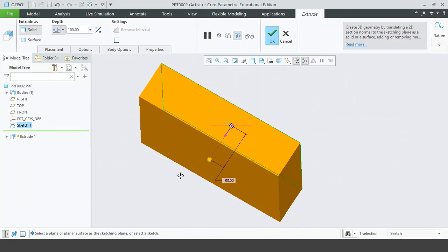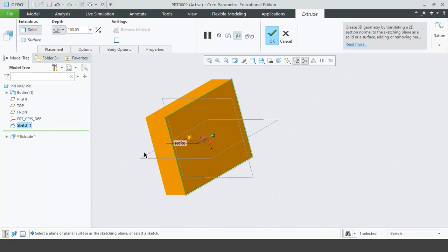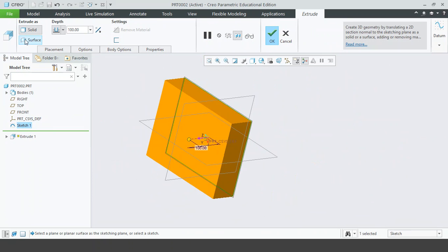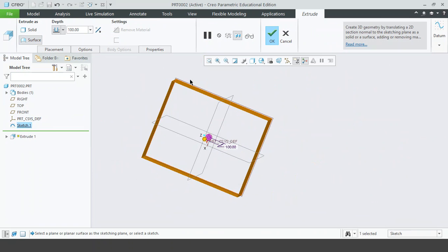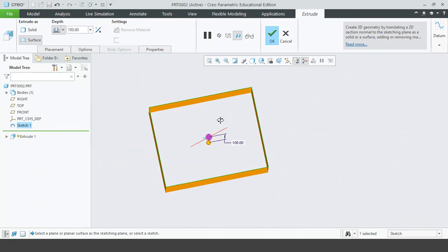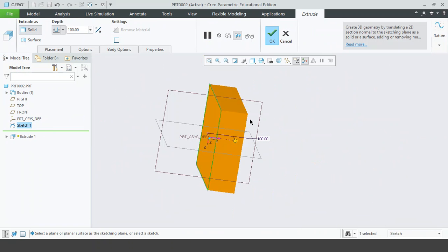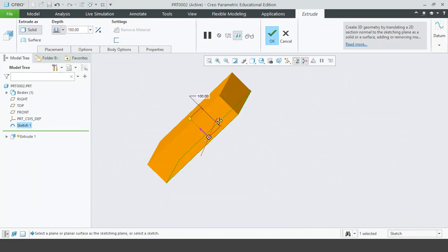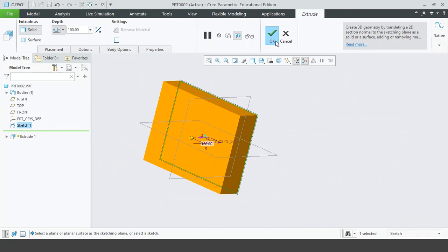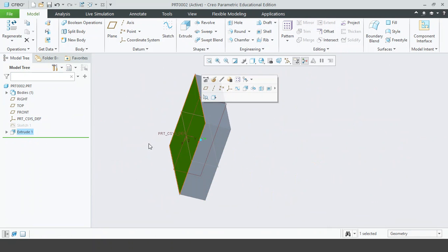Right now it's extruding as a solid, which means it extrudes every single particle, so to speak, of that rectangle. But we can also extrude it as a surface, where instead it extrudes only the outline that we drew. Of course, if you were to 3D print this, this wouldn't really come out to anything. It would instead just be a thin line of material. So for now, we'll just go with the solid. And now we have a simple cube, or rectangle shape. Now we can just click OK to finalize that. And you can see that here, now that it's gray.